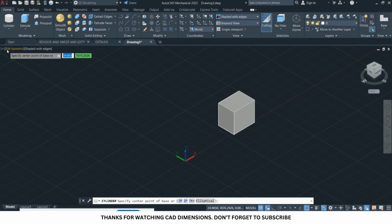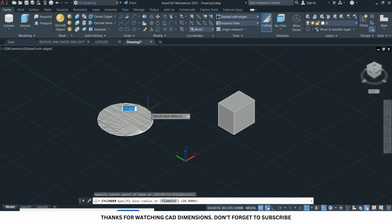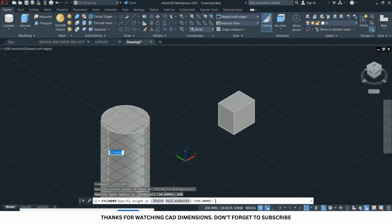So we have the next one, which is the cylinder option. All right. So I come to the working area here. I specify my first point for the cylinder. Then I'll be asked to specify the base radius for the cylinder. So in this situation, I want to enter a base radius of 100. Once I enter 100, you would see the opportunity to enter the height of the cylinder. Now if you come to the command line, you see axis endpoint.